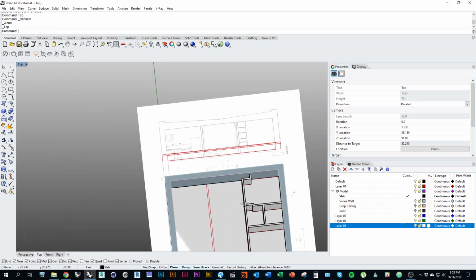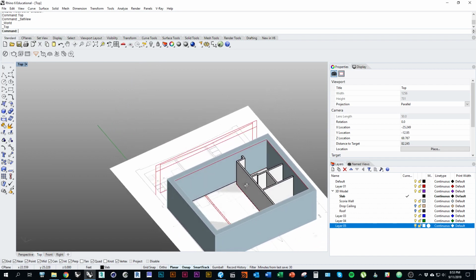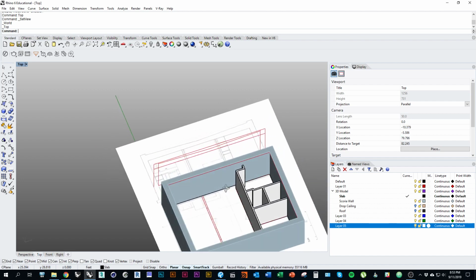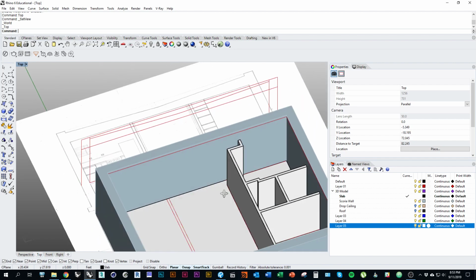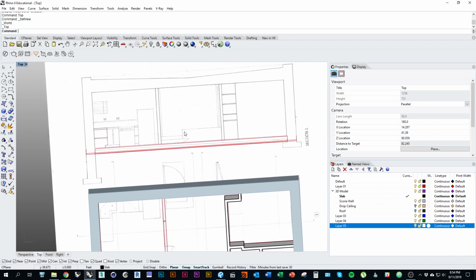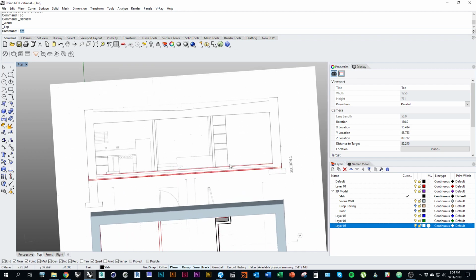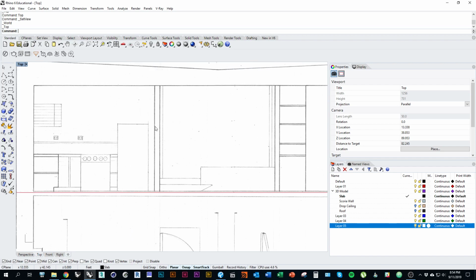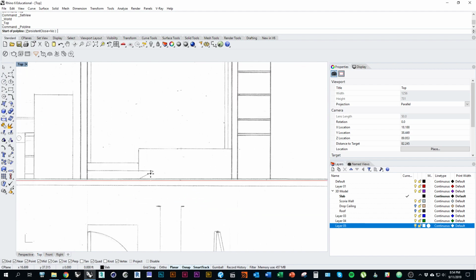And then I guess we actually kind of want to make so the openings that form the walls here are actually basically as tall as the space and span from the inside of these two walls. So what we actually want to do here, although that may not be correct for the one at the back. So that's good. Actually, what we're going to do, we'll switch into top view, and I'm going to make a polyline.